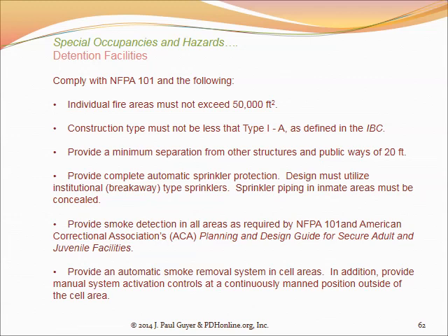With detention facilities, prisons and jails, it's almost the obverse of the typical strategy for occupants of buildings in the event of a fire, where you want to get the people out of the building expeditiously. With detention facilities, of course, the inmate population, your strategy includes not releasing them, because that's why they're in jail in the first place. So the strategy is very much to eliminate flammable materials in the detention facility so that fires just don't start.